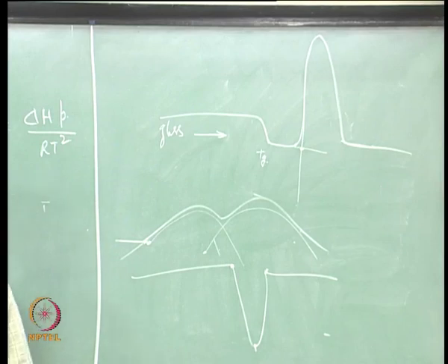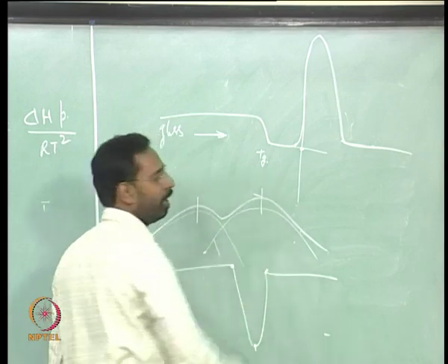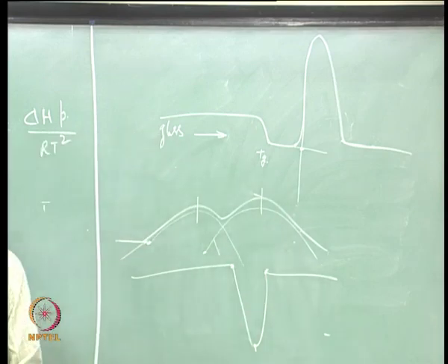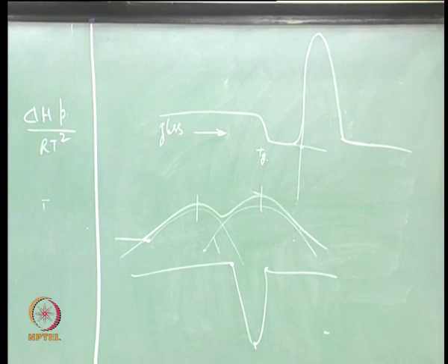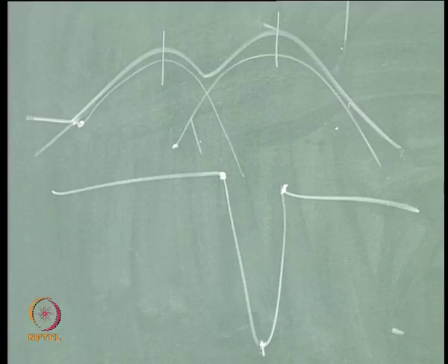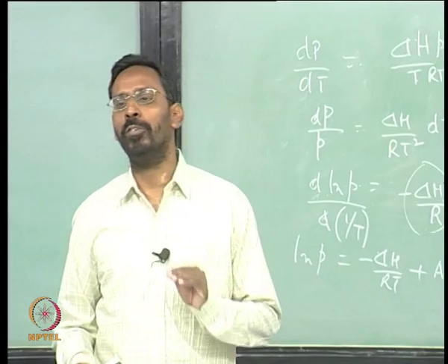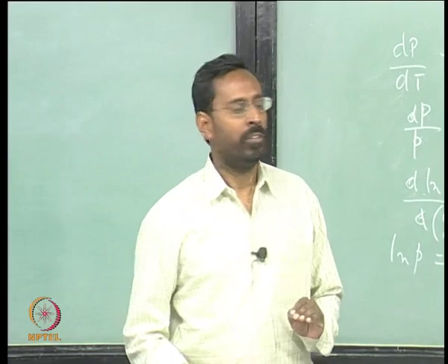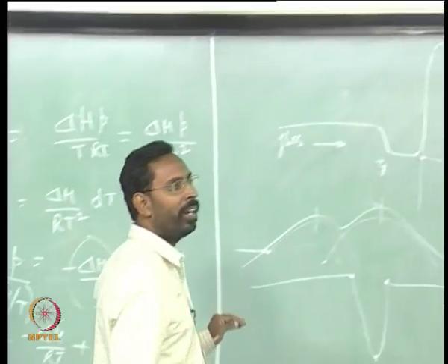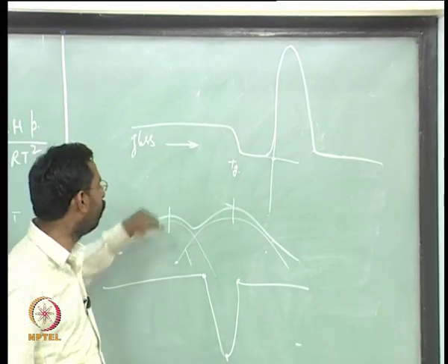Under such conditions, people usually consider the peak temperature as representing the transformation, though we definitely know the peak is not the temperature where the transformation has started. But in case it is more difficult to find the onset, we should do this.